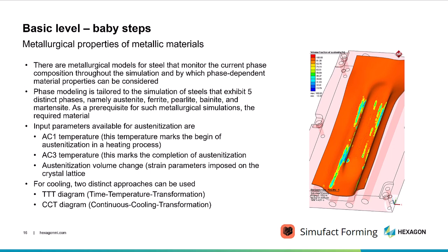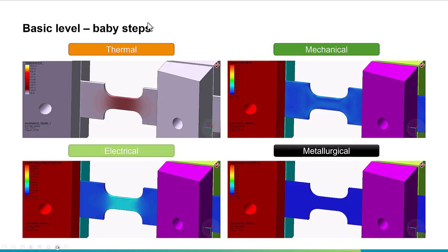You're going to need some flow curves, for example, because you want to model the heating phase and the cooling phase. You're going to need to extract that kind of information from the material that you're using to do the PHS. Now, if we think about the extreme case where you want to simulate the experiment that you're running, so you have a one-to-one match, this is an example of running a Gleeble test inside a numerical environment where you see the thermomechanical, electrical, and metallurgical process happening.